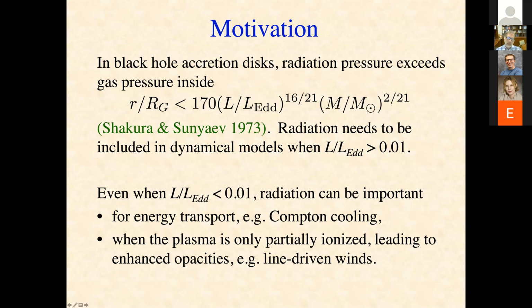This is not a closed system by itself, so you need the radiative transfer equation to close the system. In an invariant form, it's this form here, where there are source terms on the right-hand side for thermal emission and effective emission due to scattering, and also sink terms due to absorption and scattering. While this equation looks nice and somewhat simple here, actually a lot of the complexity is built into this convective derivative along the path length S.